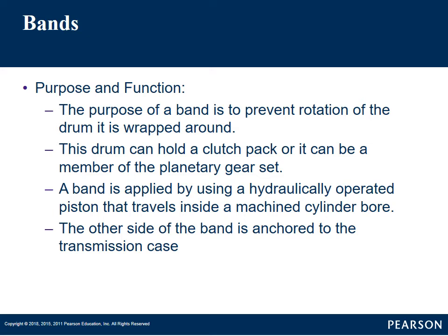Remember, if we're going to hold something, we're locking it to the case. So the band has to have some place where it's anchored. And we anchor it to the case, so when we apply that band, we're locking that part of the planetary gear set or the drum to the case, and it becomes a holding device.